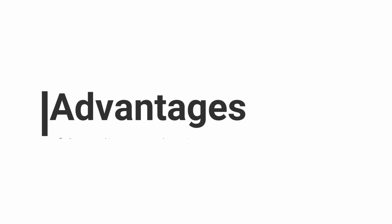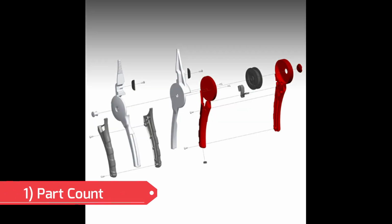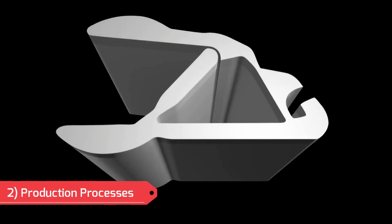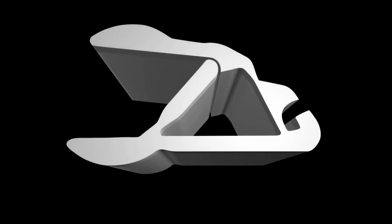There are a number of reasons why a compliant mechanism may be considered for use in a particular application. Some of them are these. The first one is part count. One advantage of compliant mechanisms is the potential for a dramatic reduction in the total number of parts required to accomplish a specific task. The part count can be reduced by shaping flexible parts instead of springs, pins, and traditional rigid hinges. Production processes. Compliant mechanisms can be simple to manufacture because they lend themselves well to various manufacturing processes.